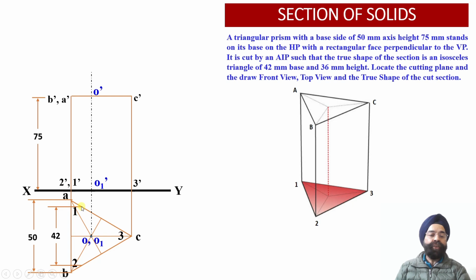So what we are going to obtain through this are 2 points of intersection over here. We can check. These are 2 points of intersection which are available with us by virtue of intersection of 2 adjacent edges of the top face of this triangular prism by the cutting plane. So point P happens to lie alongside the edge AC.